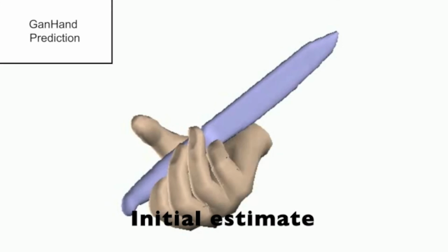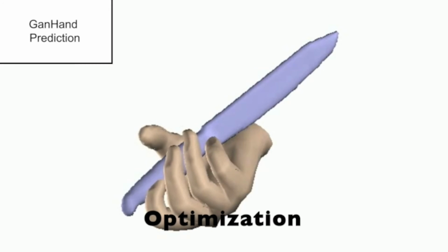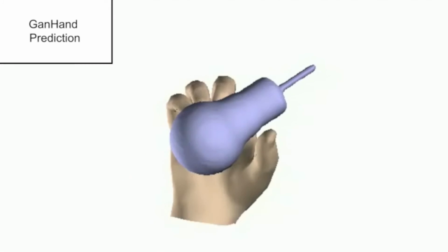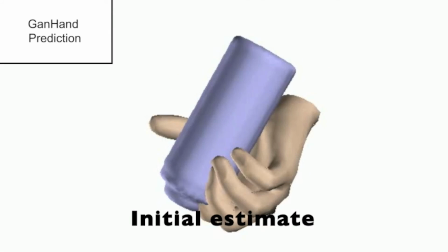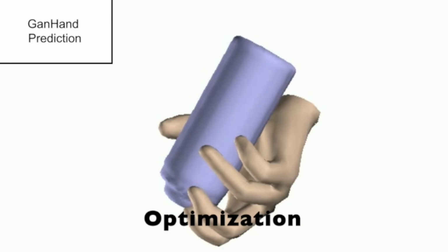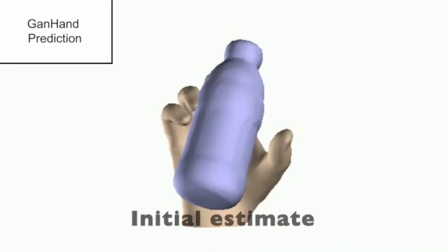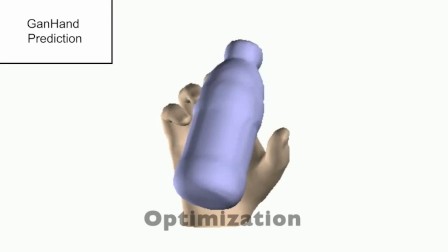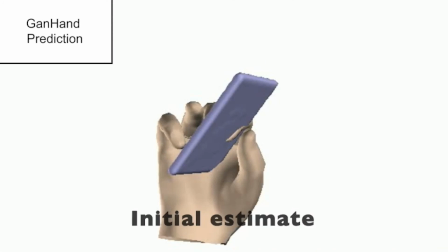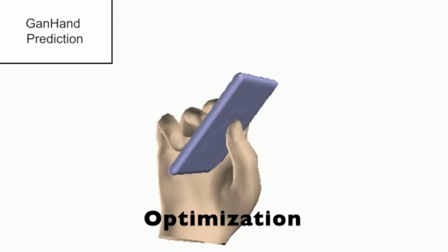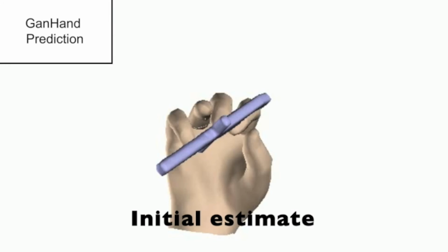After this pipeline, we combine the information of the two branches of the model and align the predicted hand mesh with the object mesh surface. In a final post-processing step, we follow the kinematic chain of the hand to bend or flex each finger. This minimizes hand-object interpenetration and maximizes the stability of the grasped object. These experiments show the effect of this final optimization with predicted grasps on ground truth objects.